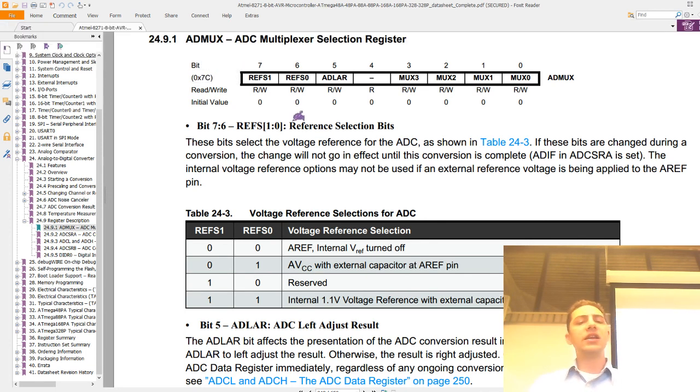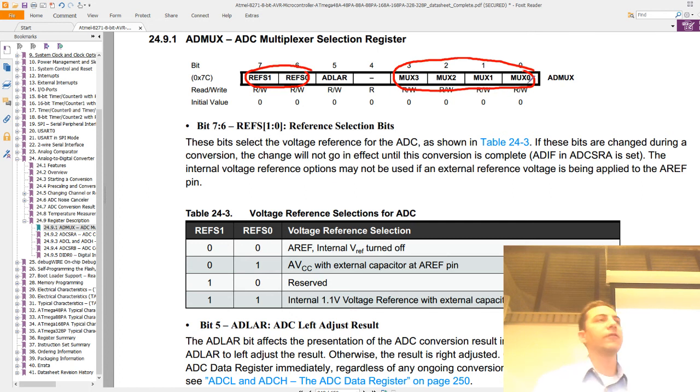When we're dealing with our ADC, a couple of things we need to set up. First, our reference. Second, our source. Our reference tells us what our maximum value can be. So in our case, we chose for lab that we wanted AVCC to be our source. That's 5 volts. This is the table associated with those reference bits. So I can tell you use whatever reference I want.